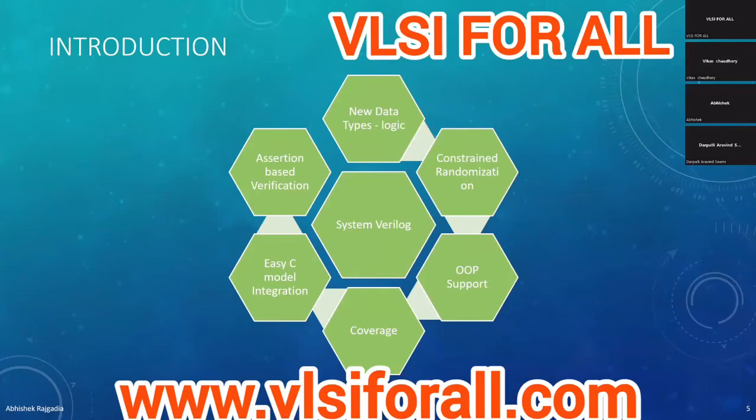So basically you are creating a golden model, and then you're comparing the design output to your golden model output. But if you don't want to model that in C, you can model it in SystemVerilog or Verilog and any other languages. But modeling any design into a C language is very easy. So people usually model their design into C and then integrate it into their test bench. So this is where the C model integration becomes very useful. This is done using the Direct Programming Interface feature in SystemVerilog.